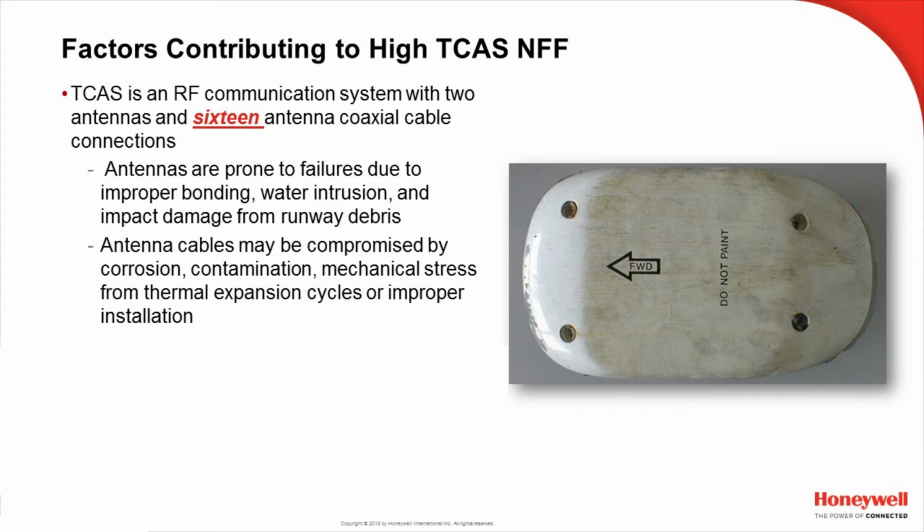Antenna cables are also something to be aware of. They are constantly expanding and contracting due to temperature changes. They can be compromised by corrosion and so forth. So be aware that the cabling is an important maintenance aspect of the TCAS system.